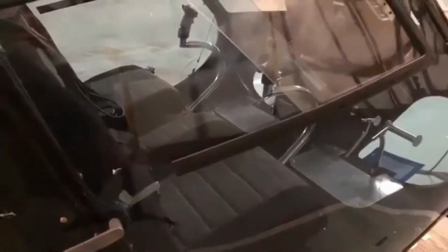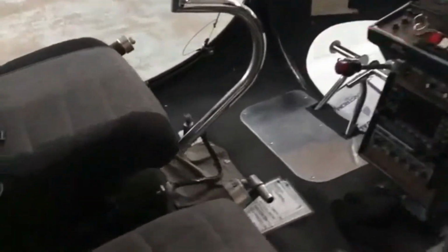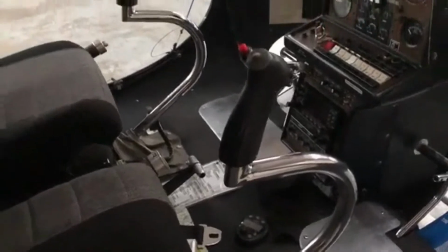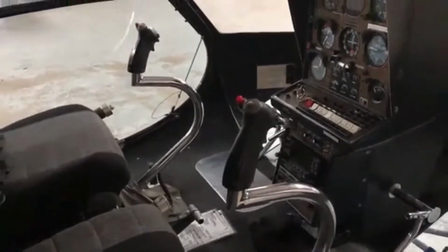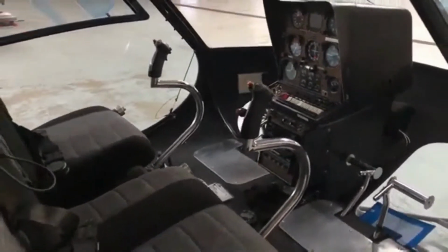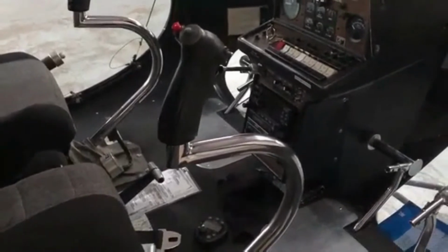So the goal, of course, is to not swing around. Students learning to hover will experience this due to too late, too strong, or too long of control inputs. So the whole trick when you're in here on the controls, the cyclic and the collective, is just to make nice, smooth movements. And as you get more and more experience, it will come, and that crazy oscillating pendular action will go away. So it all comes from just over controlling and moving these too much.